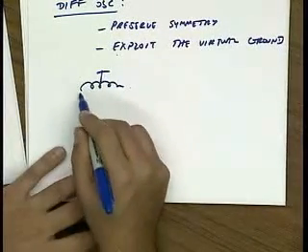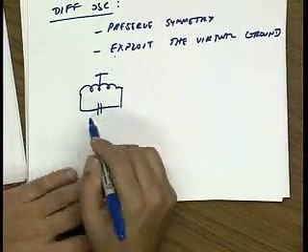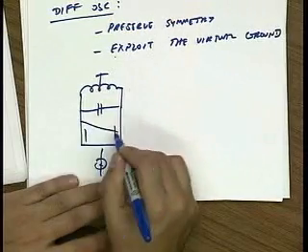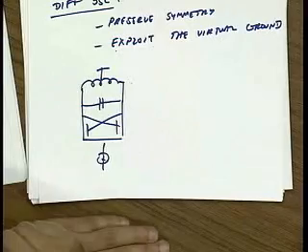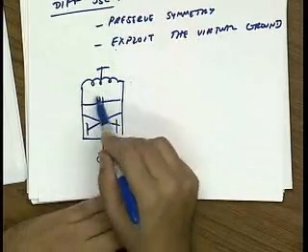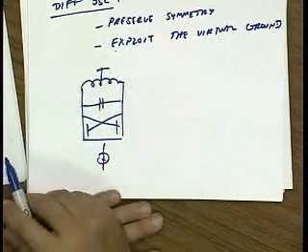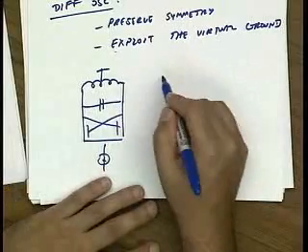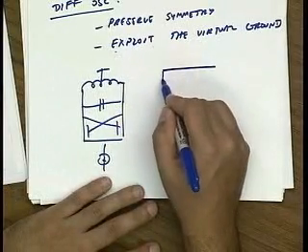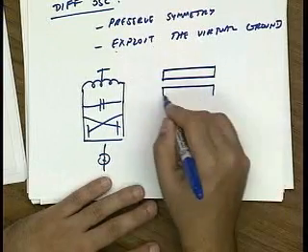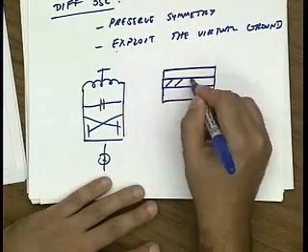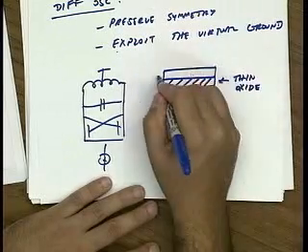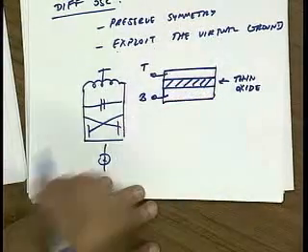So here we connect this center tapped inductor, and we put a capacitor here, and then we have our transistors again. Getting lazy today, so I'll draw my transistors like that. Well, it turns out that it's pretty hard to build a symmetric capacitor like this. Most processes, the capacitors you have are not symmetric. There's basically one version where you have a top plate, a bottom plate, and a very thin oxide. And so this is your top plate, this is your bottom plate.